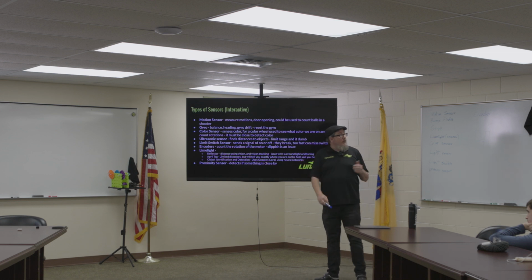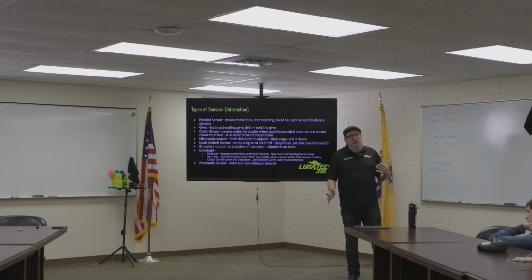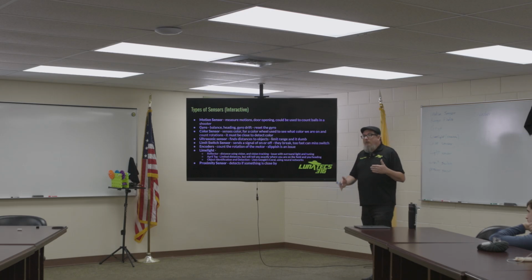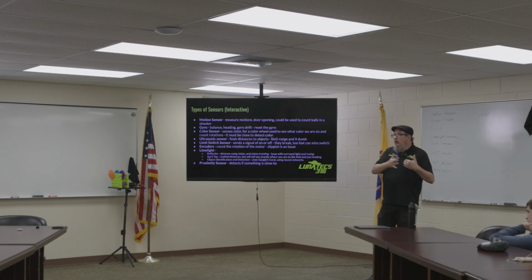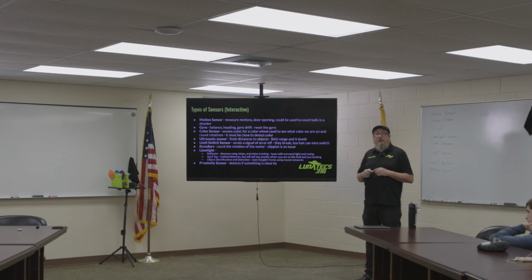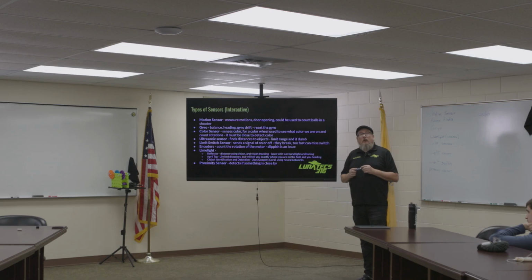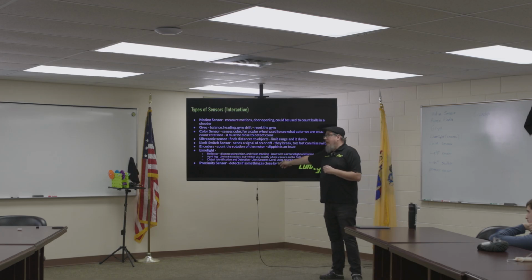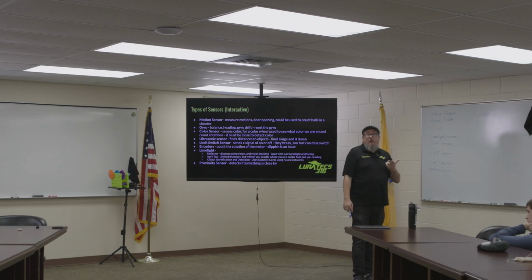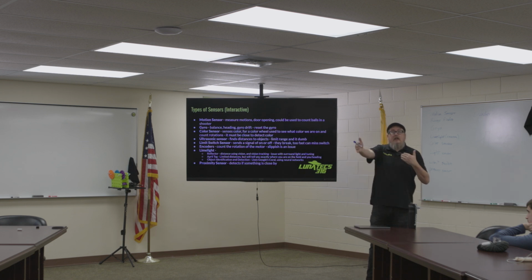Proximity sensor is another one you didn't mention, but that's kind of like a motion sensor. It's kind of like a limit switch. Basically, it will detect if something is within a certain distance of it. We've used these before as well. They're really nice. It's like a rangefinder. You're not wrong, and we've actually turned rangefinders into proximity sensors. I actually prefer, instead of getting a proximity sensor, to have a rangefinder and say, hey, do I see something within X inches of me?